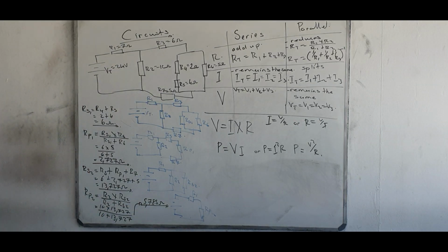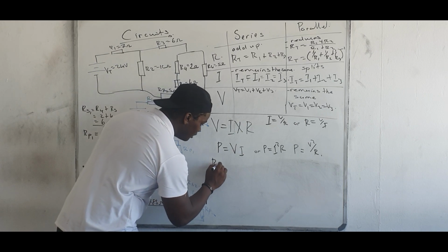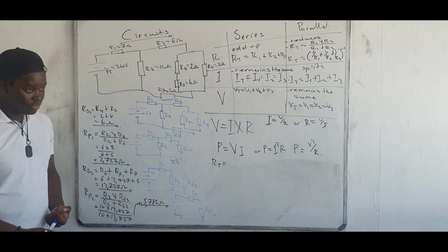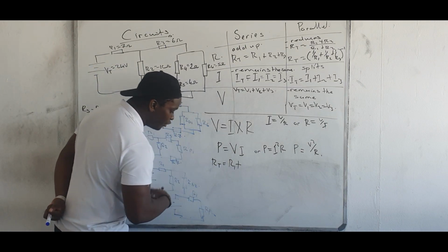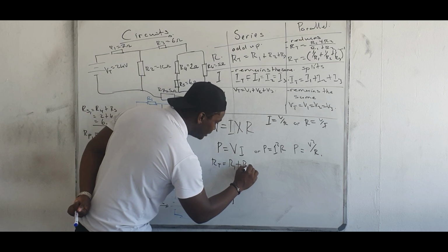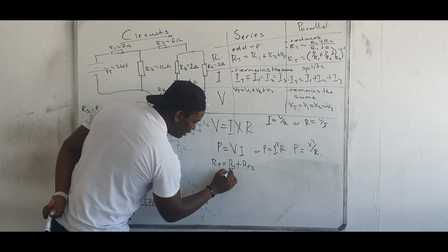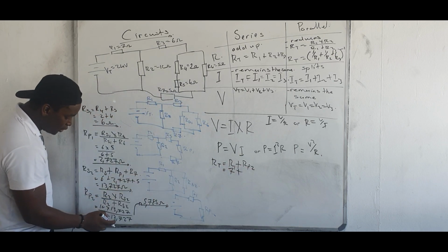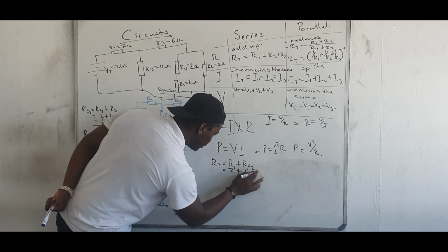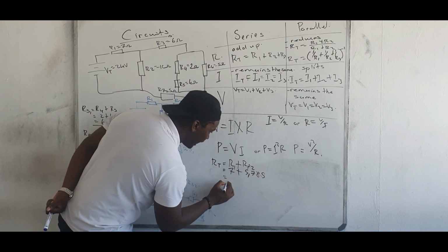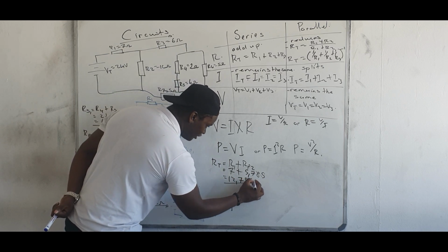R1 and RP2 are connected in series. That is correct. So RT is equal to R1 plus RP2. Are we together? Our R1 was given, and our RP2 we calculated as 5.785, and our answer is equal to the sum.